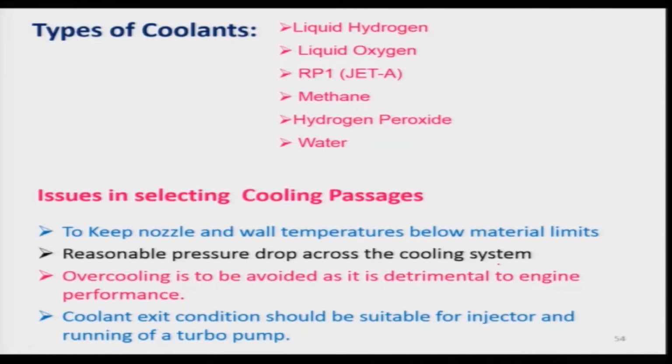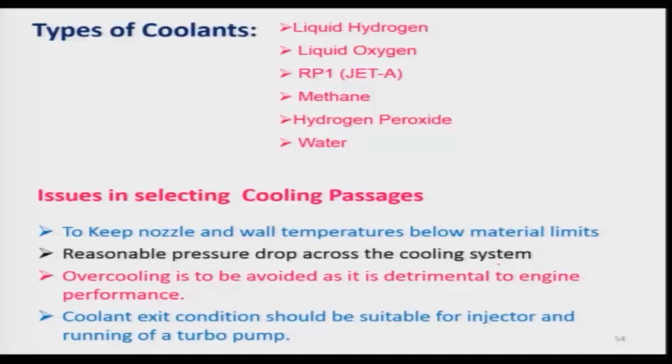So, coolant exit conditions should be suitable for the injector and for running a turbo pump, because if a lot of bubbles are created due to the vaporization of the coolant when more heat is transferred to it, then it will cause problems in operating the pump system. So, therefore, that has to be looked at, so that two phase flow with more bubbles has to be avoided.